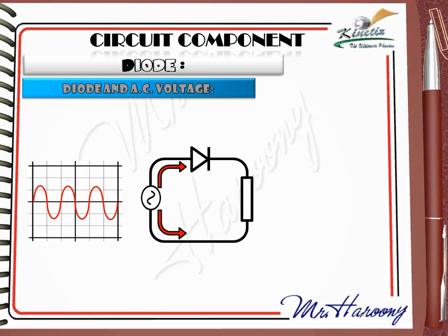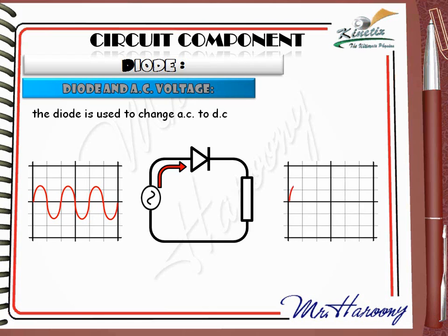The diode will allow the passage of current in one direction but not the opposite. That is why it will allow one direction to pass and the opposite current will be blocked. The current which comes with the arrow on the diode will pass, but which comes with the block will stop. Here we can say that the diode changed the AC to DC. Remember, this was the AC wave from the CRO. If the voltage is drawn by the CRO after adding the diode, this is what you will see, since one direction is allowed to flow, but the opposite will be blocked.